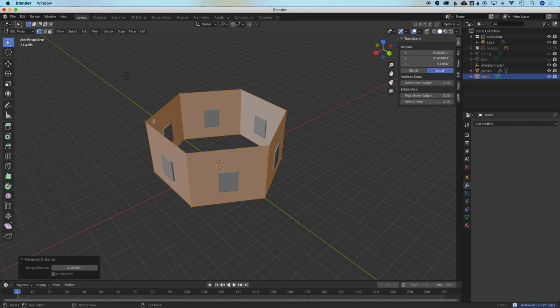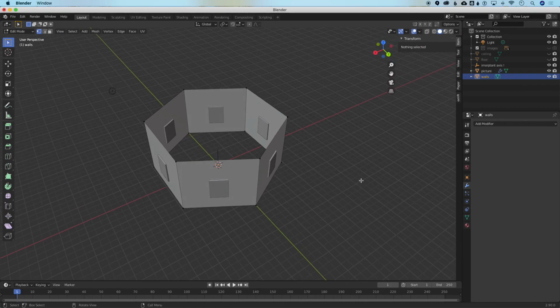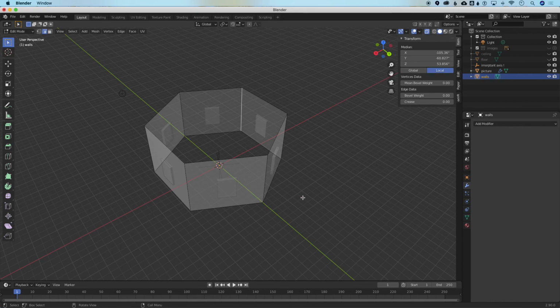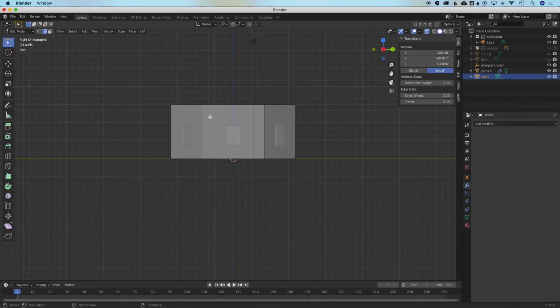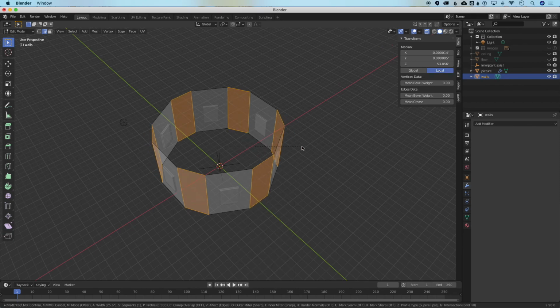And down here I can see in the bottom corner that it has removed 12 vertices from my scene. Now to test that I've put this object together properly, I'm going to press number 2, so I'm selecting edges again, and I will press Option Z for X-ray. I'm going to select all the edges in the scene, and now I'll right click and select bevel edges, and I can see that these edges bevel, which means that we have clean edges together.